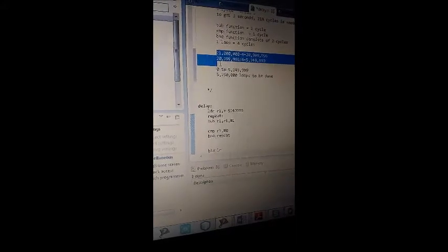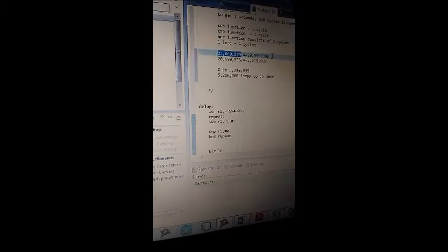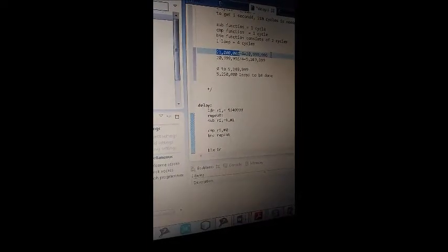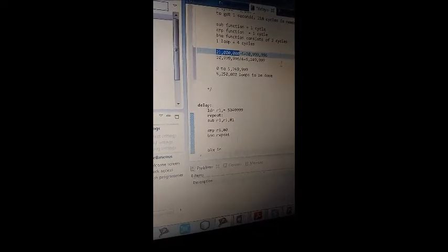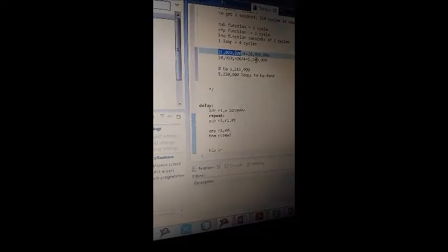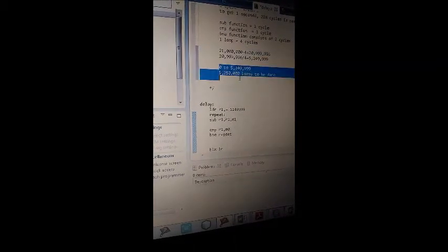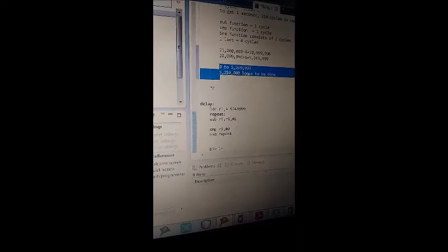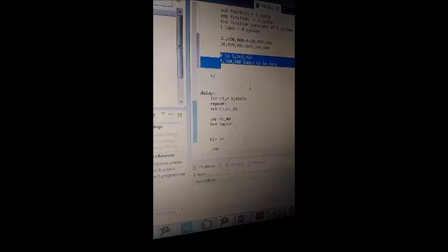First, the 21 megahertz, 21 mega, subtract by 4 because we don't want the 0. Then we divide by 4, which is 524,999. So this is 0 to 524,999. Then the 524,999 is equal to 1 second delay.